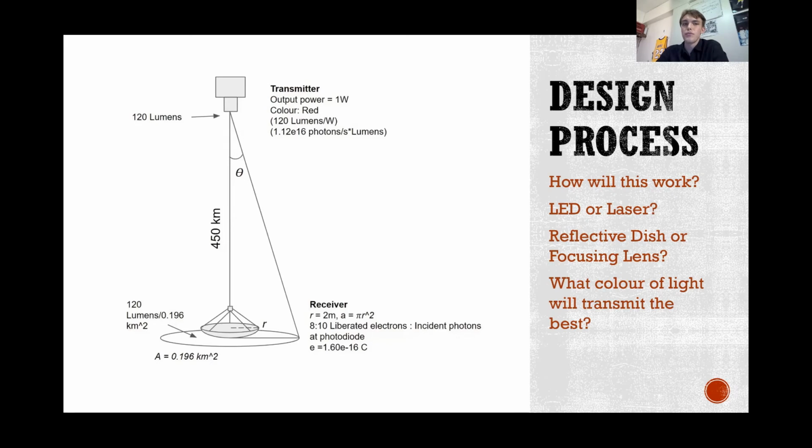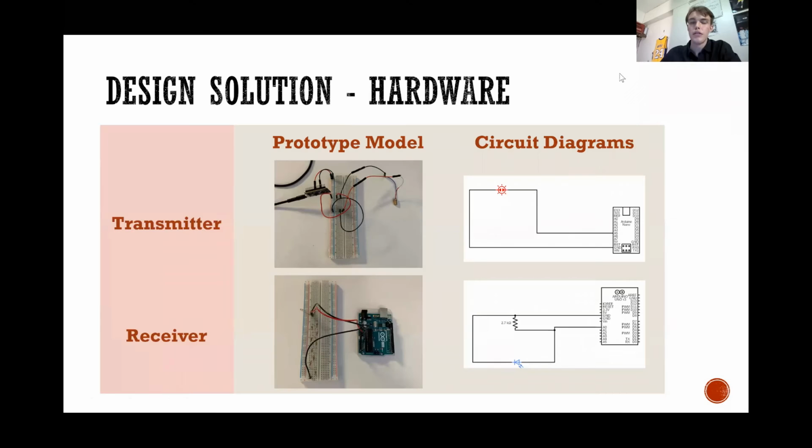Because we were only looking for red wavelengths, a red light filter can be placed in front of the photodiode to increase the relative strength of the signal from the background light. The final transmitter design also included an Arduino Nano to receive and encode the message from the satellite, as well as aerogel insulation to protect the circuitry from thermal changes and some radiation protection.